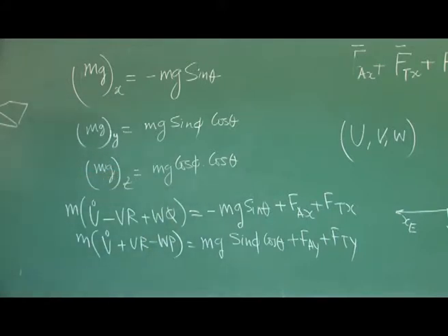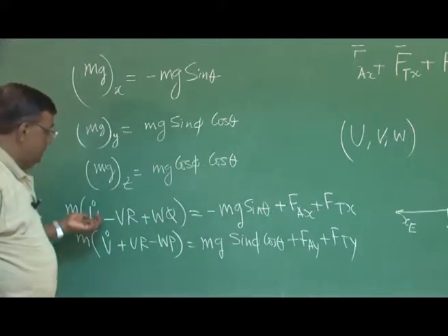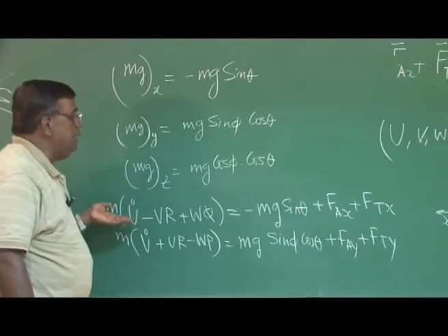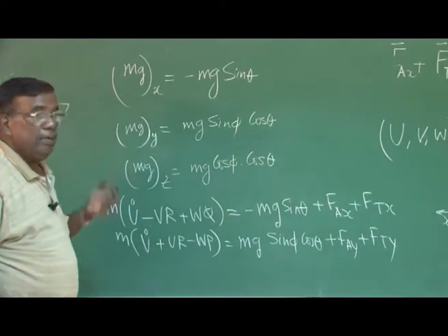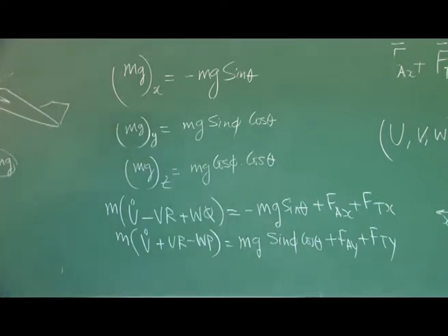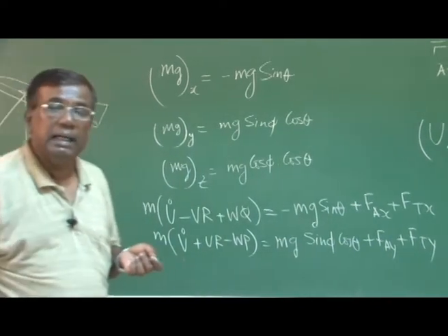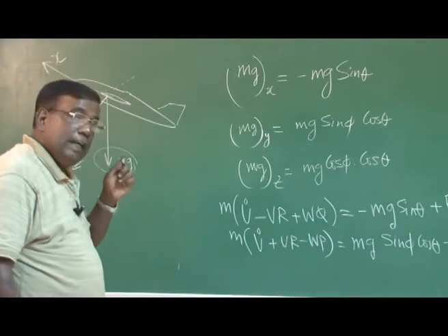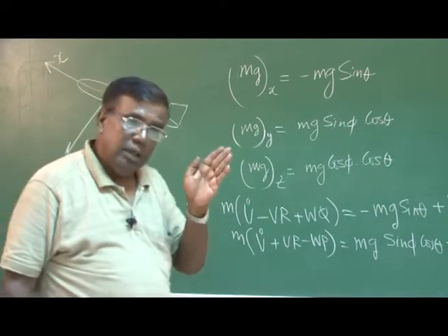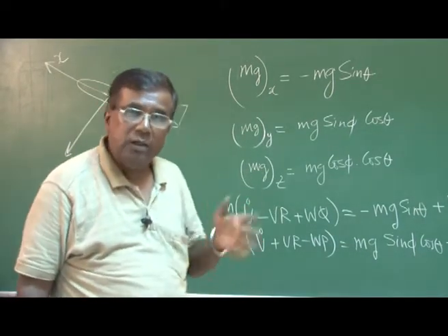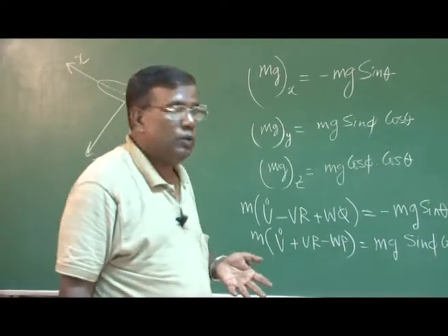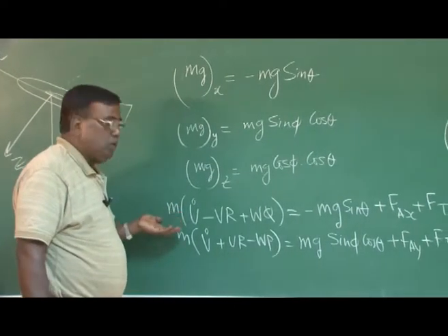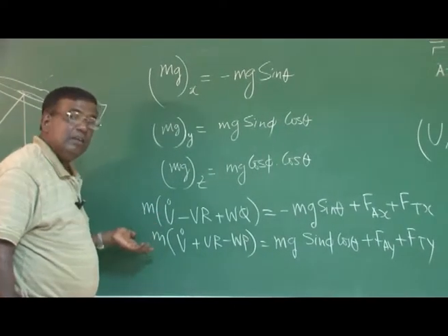But before we go further, please understand, we have not developed the perturbed equation of motion. We have developed a general equation of motion. But when I was giving you the example of the mass spring damper system, like m x double dot plus c x dot plus k x equal to f of t, there the x was measured with reference to the point of equilibrium. So, it was like a small perturbed equation of motion. So, we also need to develop small perturbation equations using these basic equations.